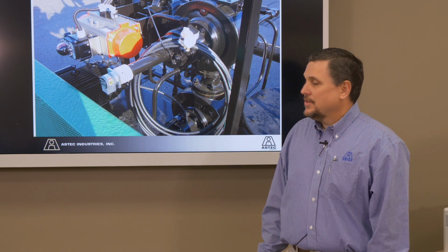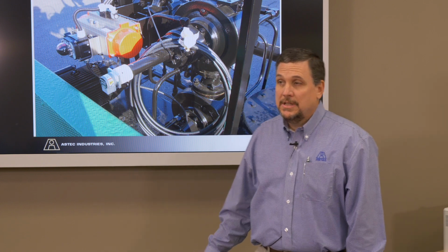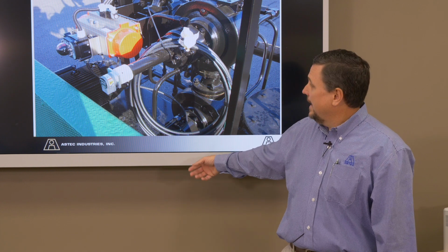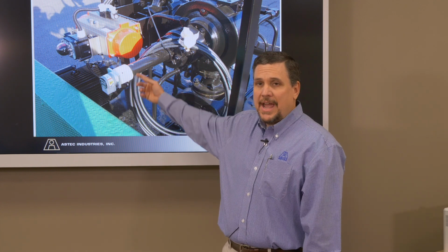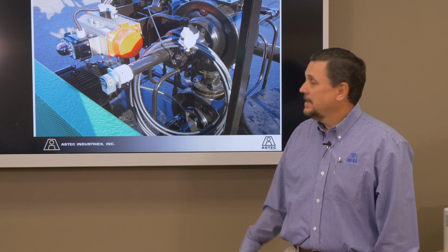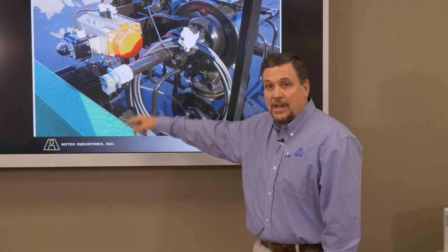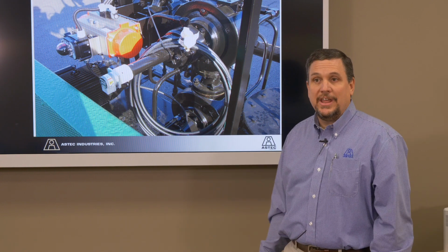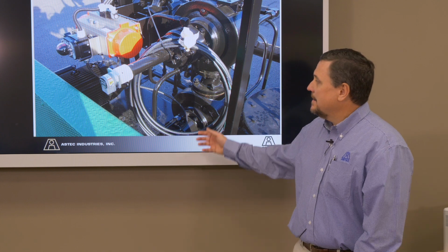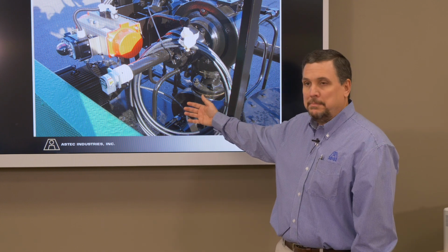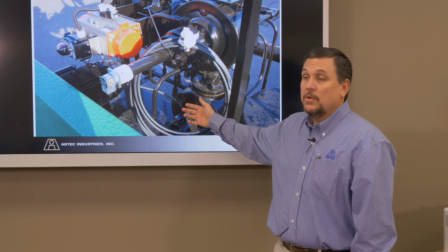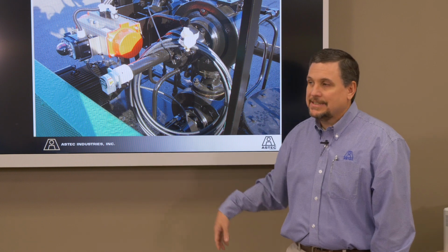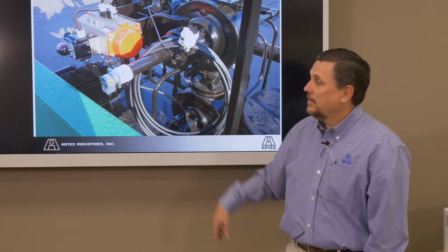One of the things that you see commonly troubleshooting these pumps, if you get a plug in a line or something like that, you'll go out and you will just do a visual check, and you can look at the shaft on this pump and you say, hey, I'm circulating at half the speed of the pump. This shaft is turning very, very slow, and this shaft down here is running very, very fast. Sometimes you can look at it visually and you can say, hey, I can see that. Most of the time that's going to lead you to the indication that this pump is bypassing for some reason, either for a worn pump or for a plug in the AC line somewhere. It's relieving itself to keep from blowing the packing out of the pump.